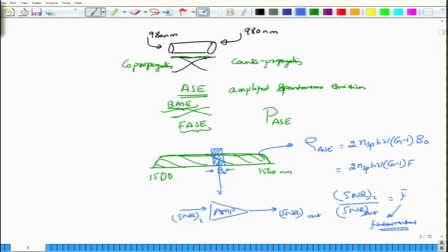It is not possible to do so. So, this noise figure comes from fundamental physics, and therefore cannot be thrown out. Now, this was actually the power spectral density. Power spectral density will be measured in watts per hertz. When you multiply the power spectral density with the bandwidth, you will get the total power, and in case of a non-ideal amplifier, or an amplifier with some noise figure F, this is the power spectral density.